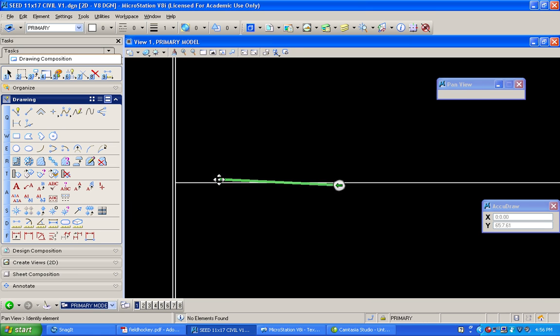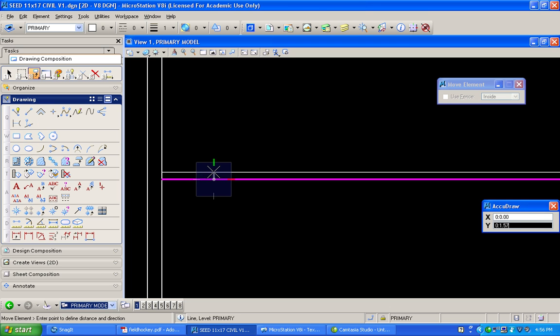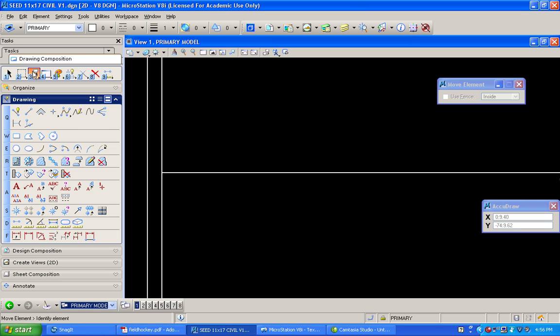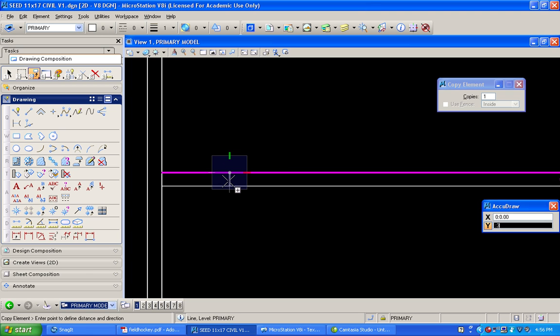Now the difference in this line is it's a dashed line, and we should make this dashed line probably maybe 1 foot lengths. So let's see, how can we do that? Let's take our smart line tool, and I'm going to hit my middle mouse button, set a tentative point here, hit the letter O, go over 1 foot, left click, come down, :3, left click.